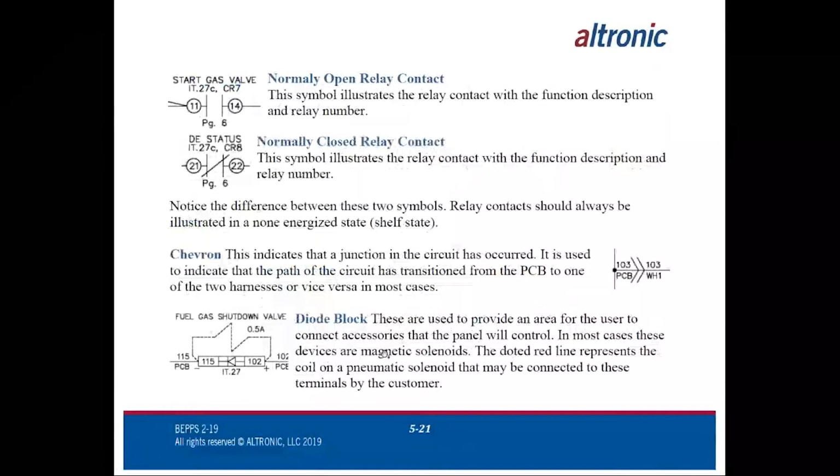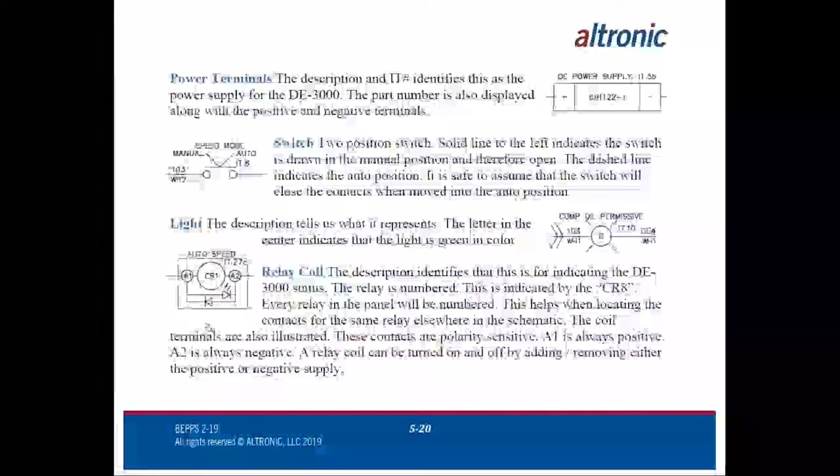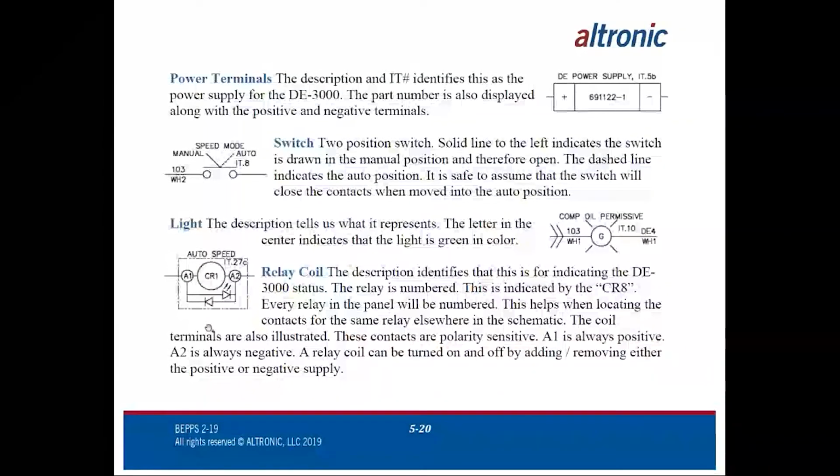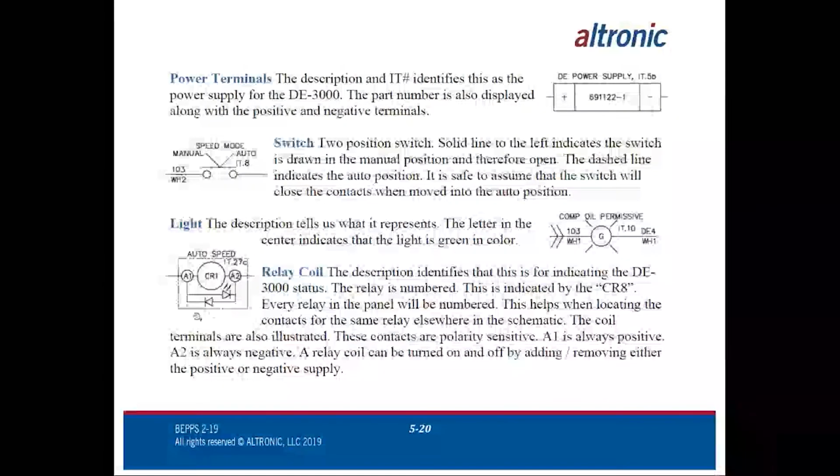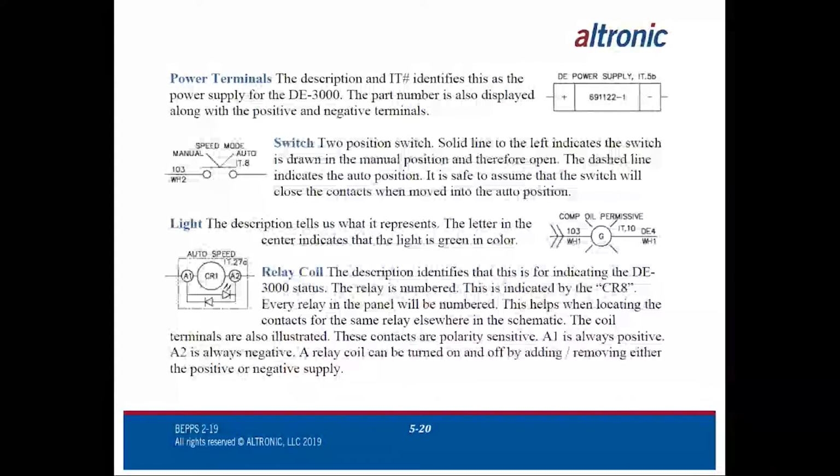Oh, one other thing. In some of the newer drawings coming out, you may start seeing page numbers associated with this. Those page numbers would show you what page to go to elsewhere in the drawing to find the contacts. So now we're going to do the contacts.